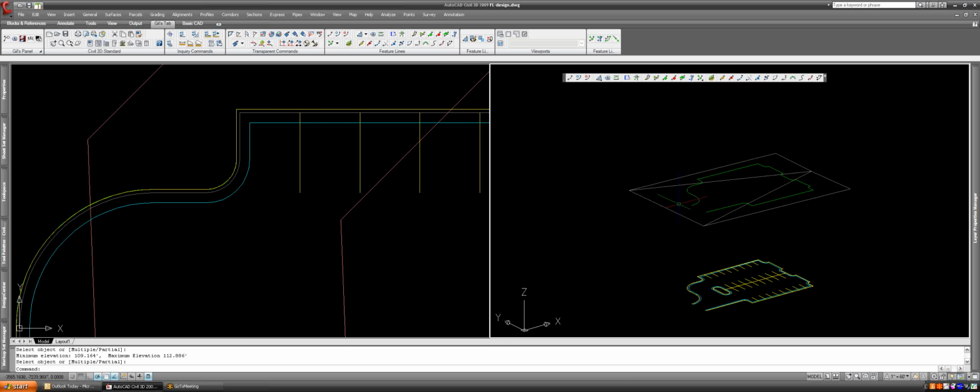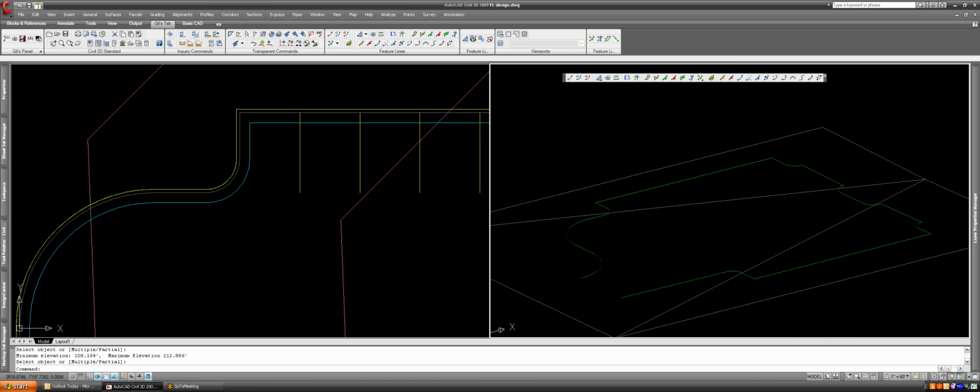And you're thinking, okay, that's great, we've got a feature line to the surface. Now we need to make the face of curb, the bottom face of curb, and the gutter. What tool do we need to use now? We are going to use this tool right here called Step Offset. What this allows you to do is create another feature line from a feature line using different elevations. So select offset. We're going to select it here in plan view so it's easier to do.